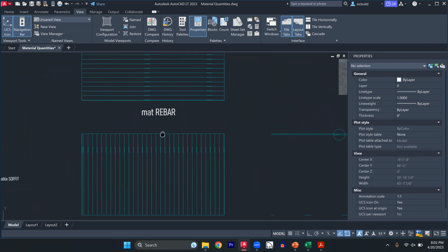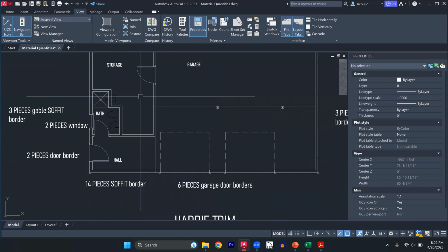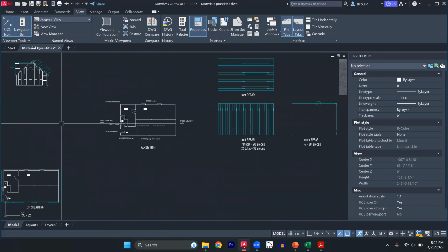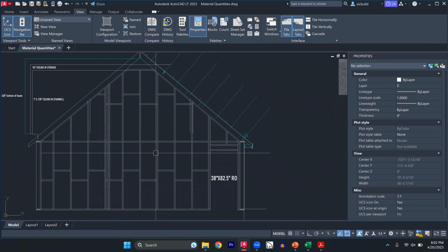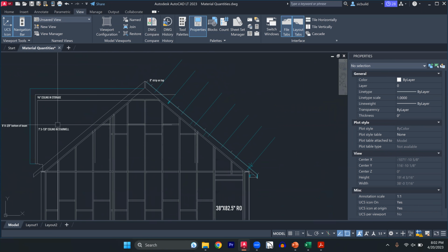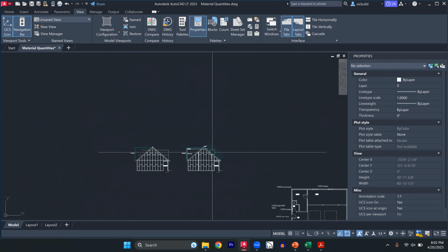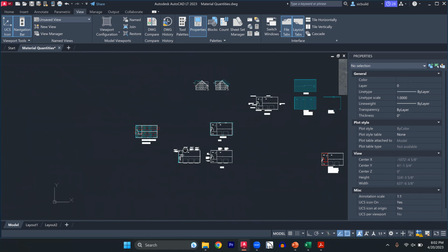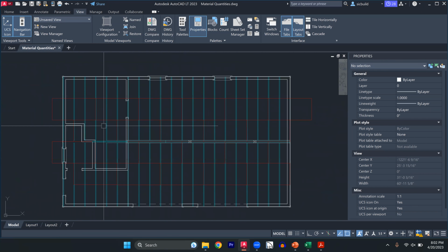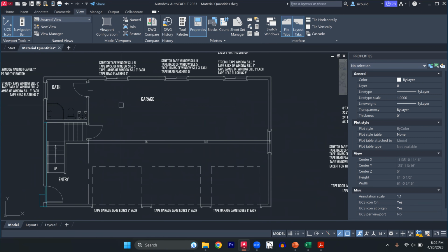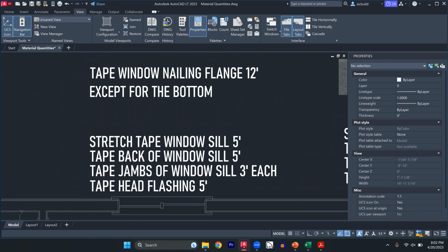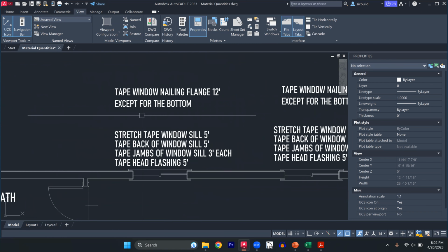I've got rebar for the mat of the foundation. I've got more headers in here. I drew some tall walls to figure out, there's a stairway here, how tall my studs were going to be, special numbers, my roof sheeting, all kinds of stuff is on here. The second floor had some sheets. They wanted partial flooring in here, so I figured out how many sheets I need doing that. I figured out how much tape I need to go around to tape all my seams off around windows and stuff like that.